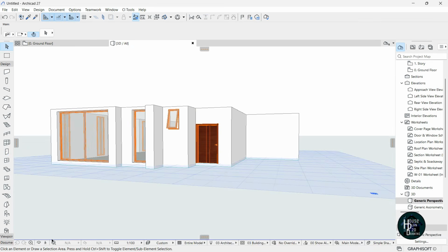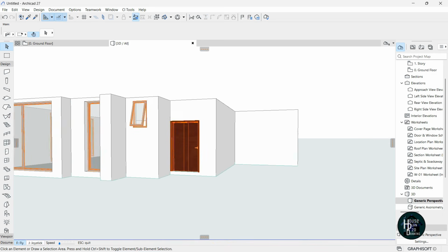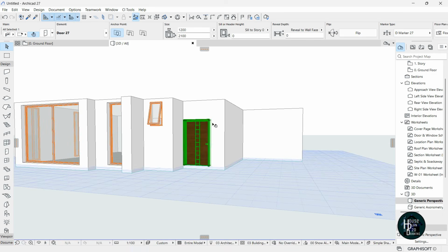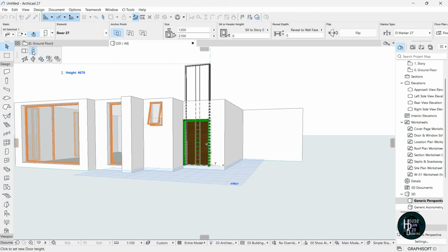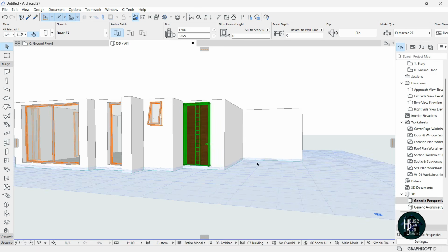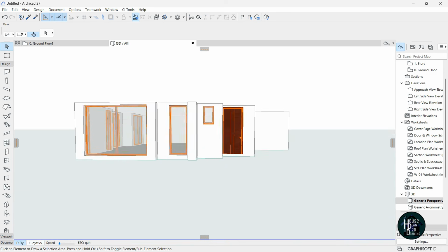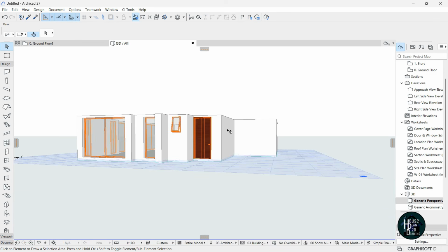Now the next thing you want to do concerning this is try and increase the height of this. Click this, click on this node here, make sure you are selecting stretch vertically, and as you are increasing the height, come to this side here and click. Once you click, it's going to level with the window over there. So we've accomplished this. What we want to accomplish now is the window by this side here.